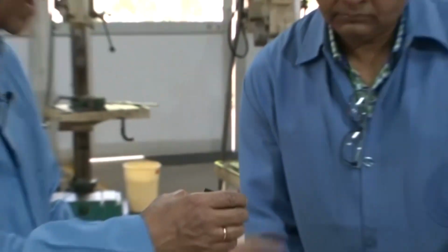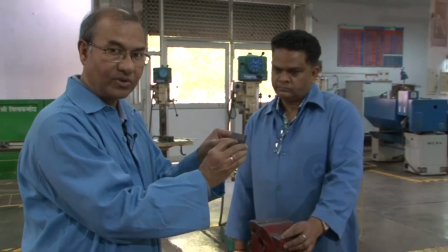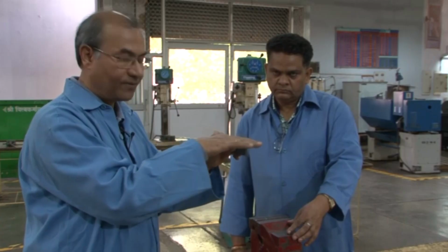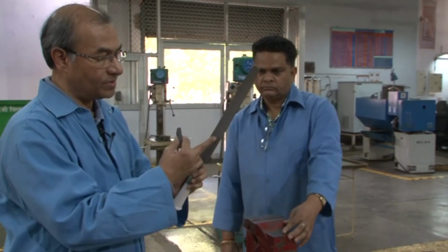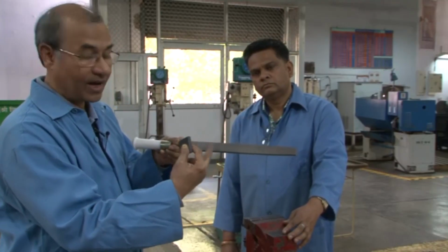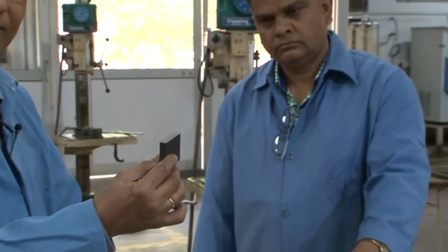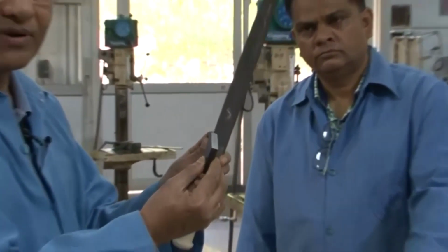Aman Singh will demonstrate. This is the vise. In this vise this job has to be mounted, and then it will be filed manually, first with the rough file. I have shown it to you there. You can see closely that this is a rough file and this is a double cut. And after that, when sufficient material has been removed, the final material removal will be through the fine file.